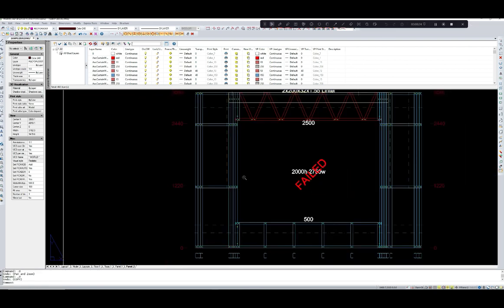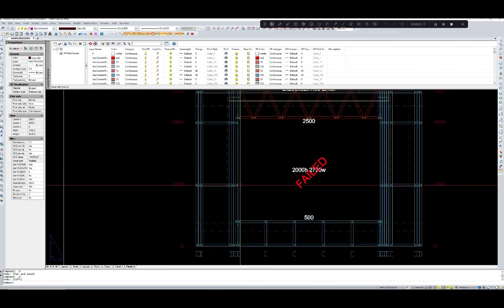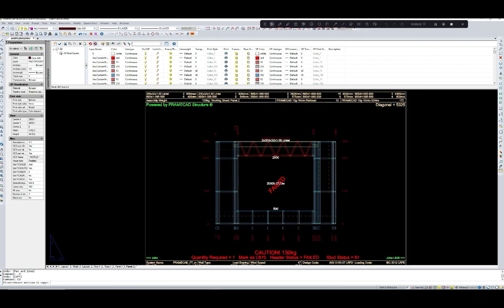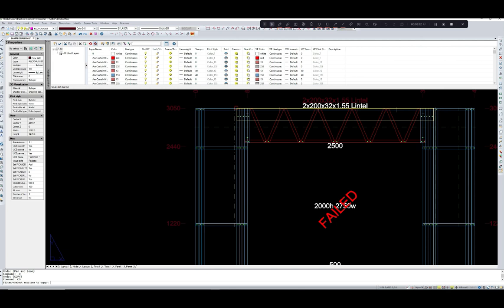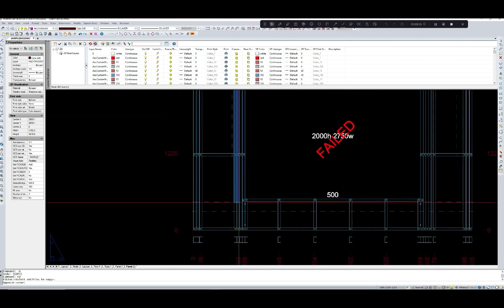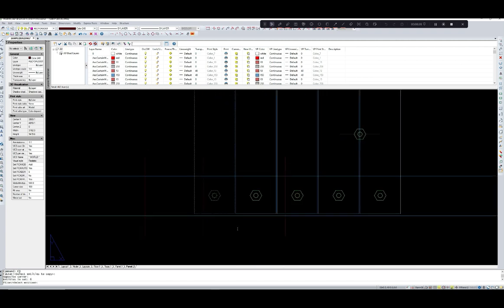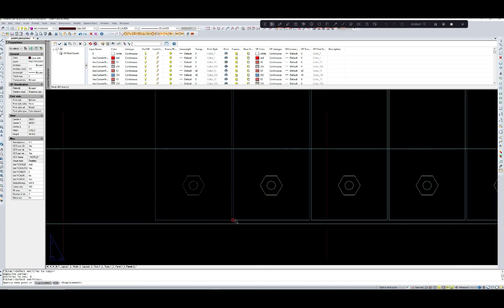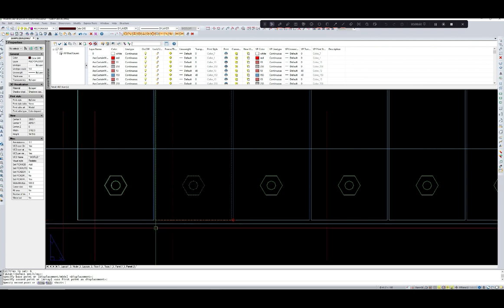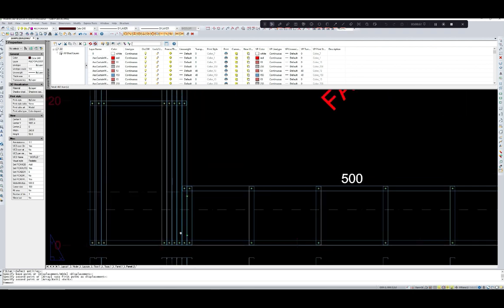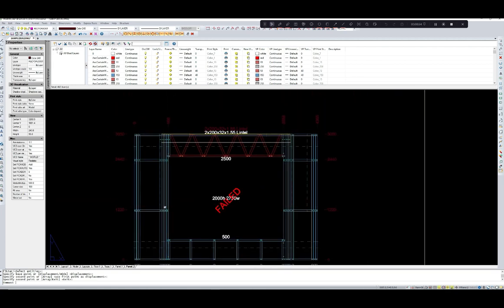So suppose we want to add a stud, so copy a stud. Use the command copy, select them with the screw as well. Now take a base point from the nearby stud so that the gap is maintained. Now choose the destination point and place it, and then enter. So a new stud has been added.